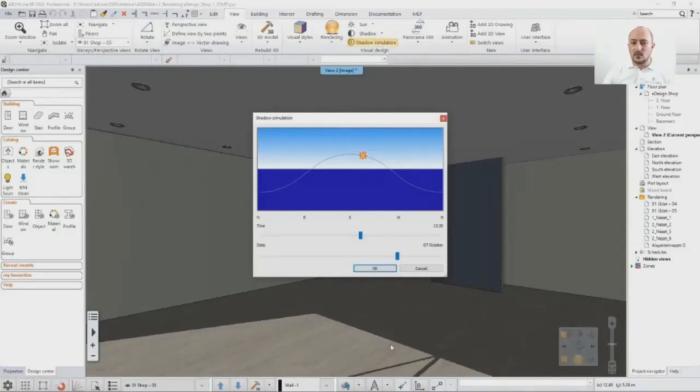And well, this is something that you would like to consider balancing with, because the sunlight is very, very powerful. Even if you have a lot of light sources all around you, those are not having enough power to suppress the sunlight. And even if they do, the sunlight is having a very, very important effect on your rendering. So you should consider whether you would like to let the sunlight in and brighten up the areas, sometimes risking burning out surfaces because it's too powerful, or you can just select another date and time. And it's an important thing here.